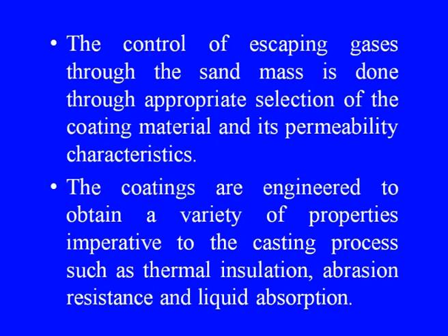The control of escaping gases through the sand mass is done through appropriate selection of the coating material and its permeability characteristics. The coatings are engineered to obtain a variety of properties imperative to the casting process, such as thermal insulation, abrasion resistance and liquid absorption.